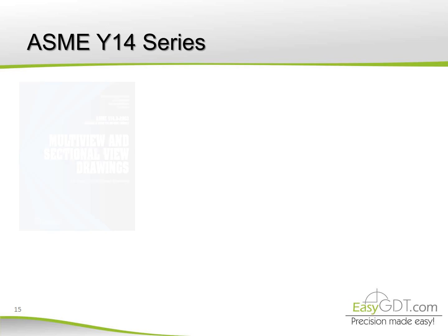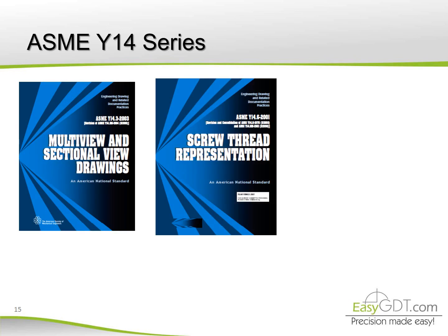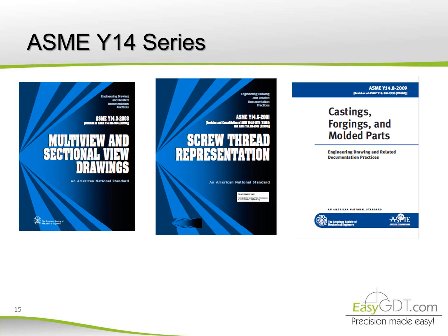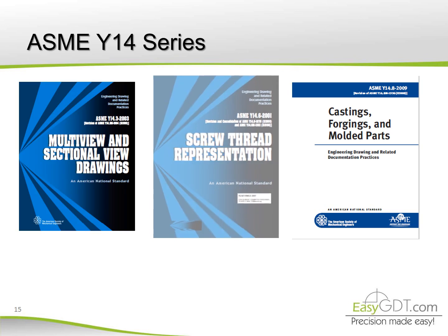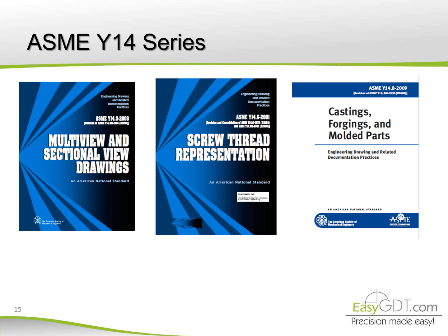In the Y14 series, we can find all the engineering drawings standards for machine parts, metal and castings, etc. Here you can see the ASME Y14.3 related to multi-view and sectional view drawings, 14.6 for screw thread representation, and 14.8 for casting, forging, and molded parts drawings.